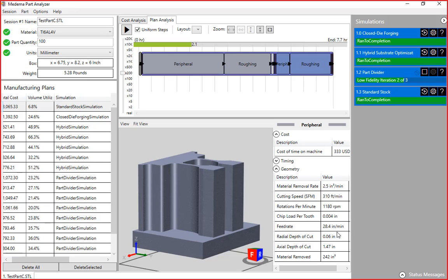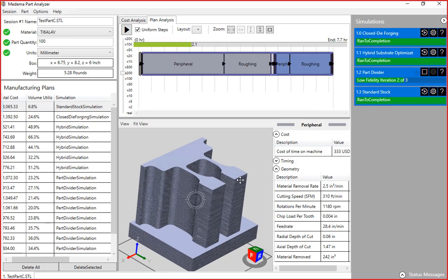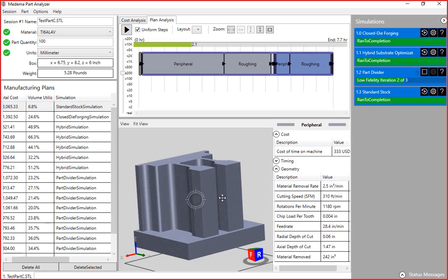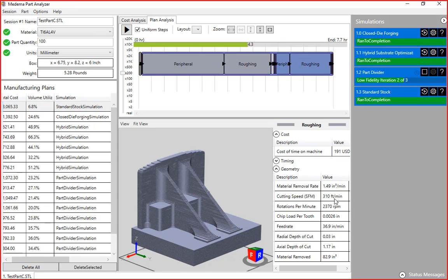And so some of these inputs are from the tool manufacturer, and these are all in a spreadsheet that could be customizable to each individual customer, or we could pull them from suppliers like Kennametal. And then for each of these different processes, you'll see these numbers change accordingly. So in that case, peripheral milling was the highest material removal rate, and then roughing, and then finishing gets slower.